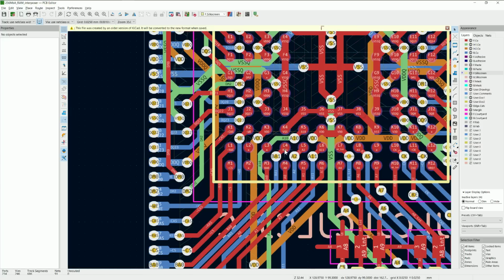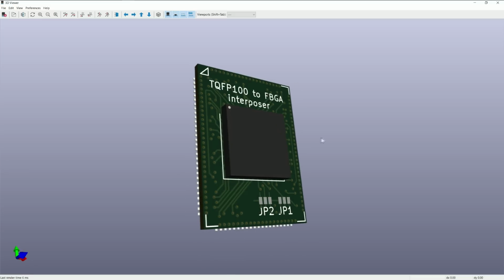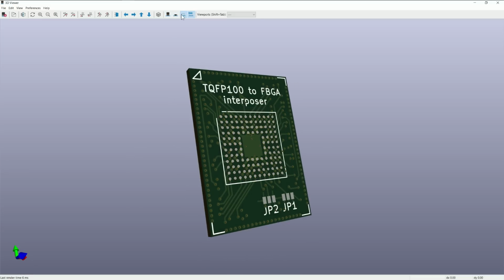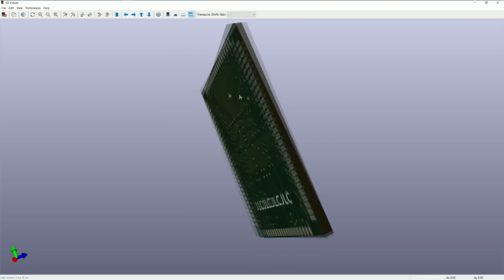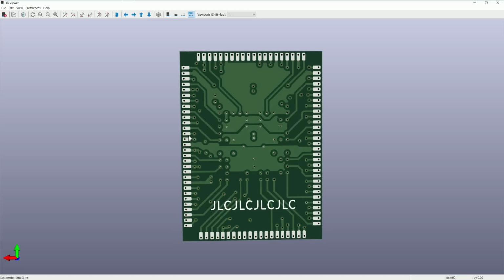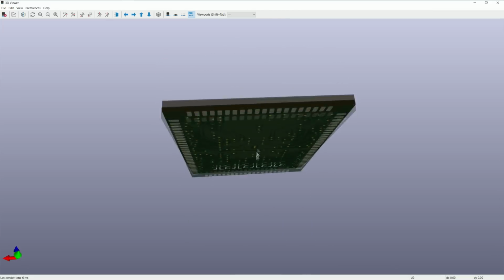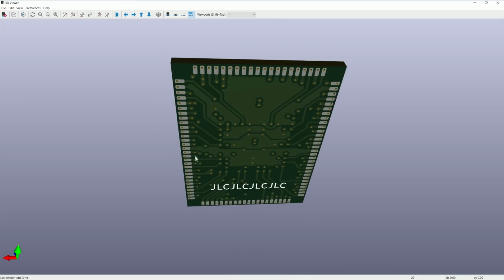So this one is 4 layers, and you see sometimes there is some contention in those layers. You have to snake some signals in and out. But really it wasn't too challenging. Going to the 3D view, we can start to see what this is going to look like. One thing to work out is how to connect this to the Xbox. So in this case, you can see I've put these very short pads on the bottom side. So this is going to surface mount onto the motherboard. My problem is that's going to be very hard to solder.